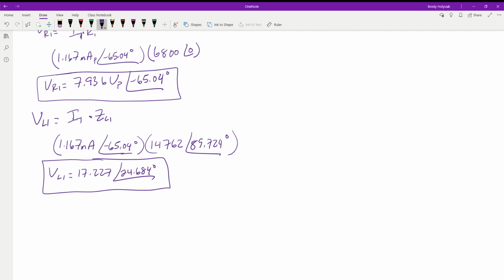And remember to find the phase angle as the difference in time between your reference line and the actual phase angle of the component you're measuring. So you'll put your lines on your scope for setting time in the vertical position. You'll set when it crosses the x-axis for both those lines and find out the total distance in between.